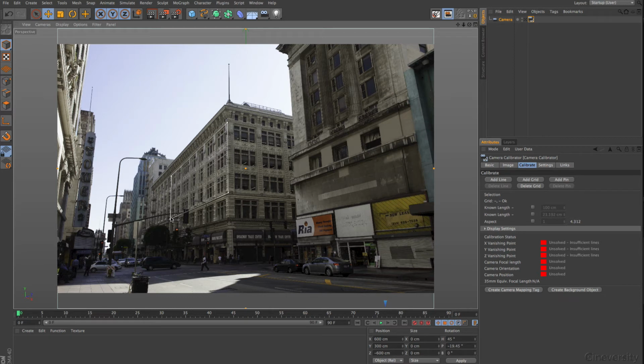I check where I am with that. That's pretty much there. And I take some time because that's really the main information that you give to the calculation. If these points are not set very, very precisely, then the calculation will go wrong because it assumes the picture has a different perspective distortion. So nothing happens here, because it has no idea where the orientation is. And we give that to this system when we press down the Shift key and then click on one axis, and take a look.